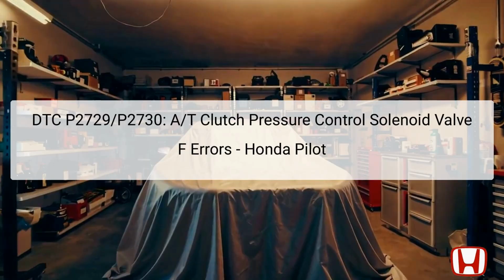The diagnostic trouble codes DTC P2729 and P2730 indicate issues with the AT automatic transmission clutch pressure control solenoid valve F in the Honda Pilot model from 2016 to 2022. DTC P2729 signifies a low input signal from the solenoid valve, while P2730 indicates a high input signal.